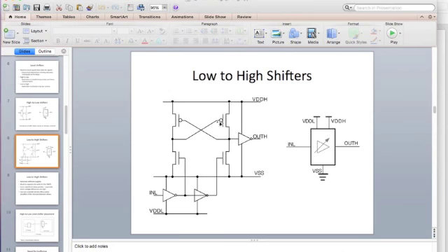what is called a half latch, where you have a cross-coupled PMOS, and the cross-coupled PMOS essentially helps to pull up the PMOS completely to shut it off, so that you don't have the leakage current. So how does it work? Let us say that this guy is 0 and this guy is 1. That is the initial state. Now when the input comes, it turns this on.